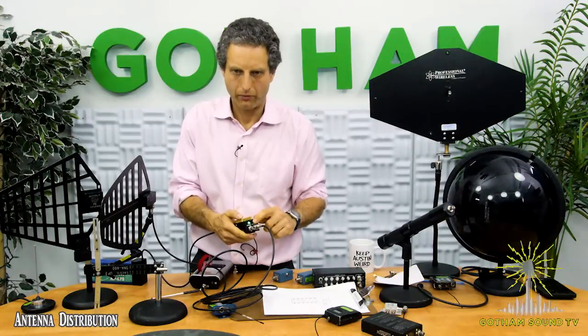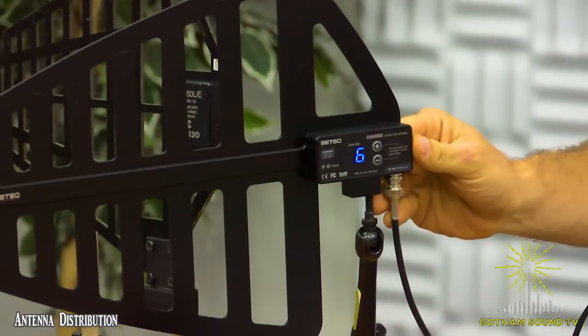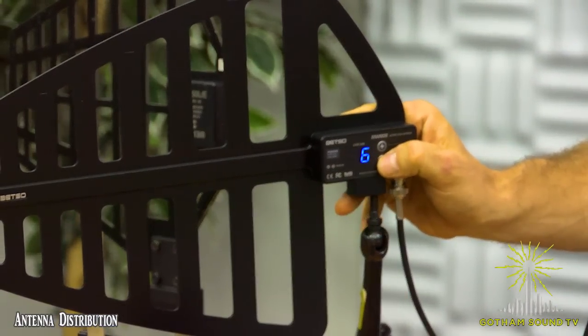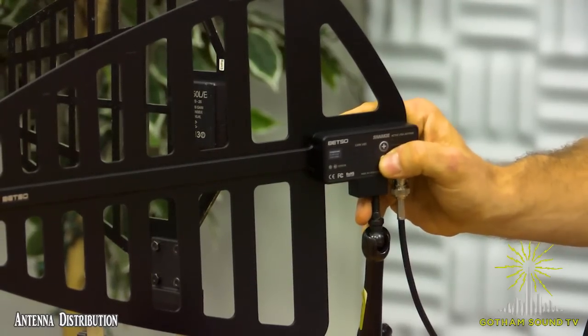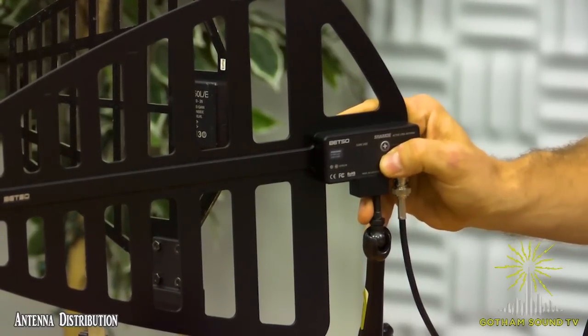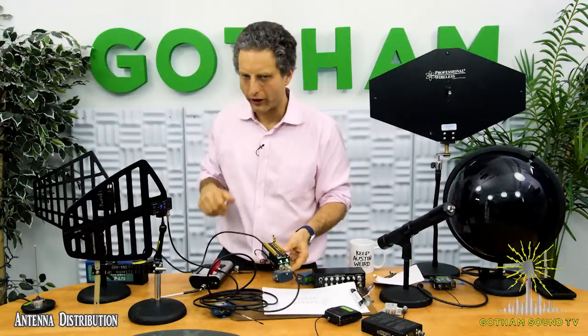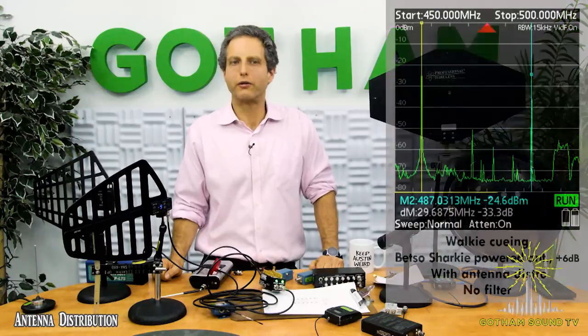I'm going to turn on power, and when I turn on the power, yep, this becomes hot. So this was as we left it at 6 dB, but you can actually dial the gain up or down. You sort of hold it, and then you can dial it. And interestingly, this can go to negative numbers. So in that case that I was describing earlier, where you have a huge broadcast tower that you're in the vicinity of, that might be a super helpful thing to be able to do, to dial the gain down. So let's look at the first slide.